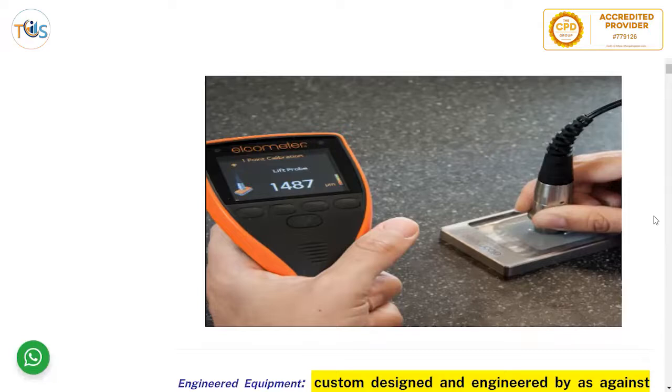So once you apply the paint and the solvent evaporates, the solid part remains. It might be 40%, 30%, or 50% of the whole paint. So it's normal to say that 40% of that would be remaining, and say 60% will be evaporated eventually, because then the thickness would reduce accordingly. So if the wet film thickness is say 100 micron, and it was a 40% volume of solid, only 40 micron remain after evaporating the solvent.